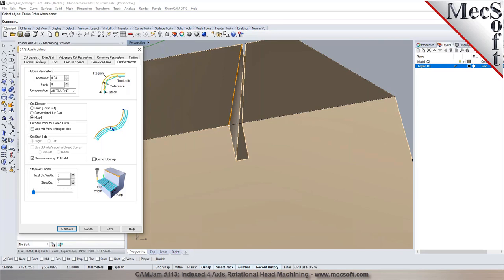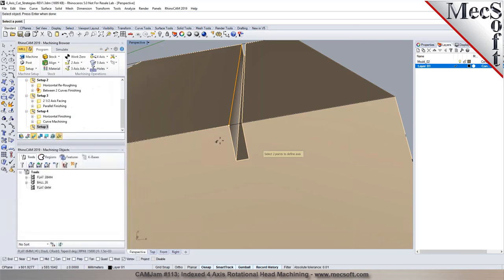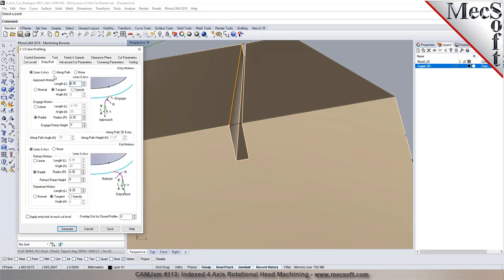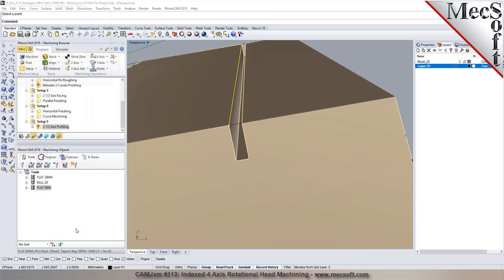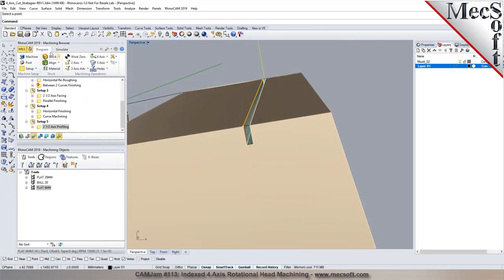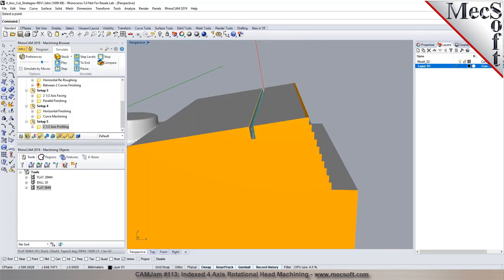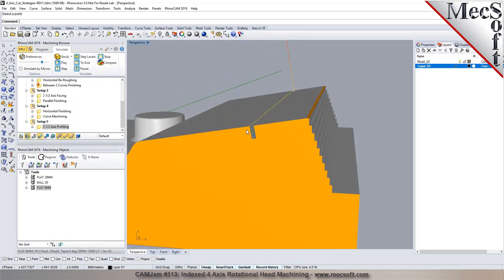And you can choose the cut levels in here. So when you measure the depth, it's going to be along the tilted plane. Okay. And you can say you want to go in multiple steps of 3 millimeters each. You can control your entry and exit however you want it to. Lead in, lead out, so we can have a slight retract outside, so it gives you a nice clean edge, and then generate it. So that'll give you a profile cut at that angle. Yep, perfect.